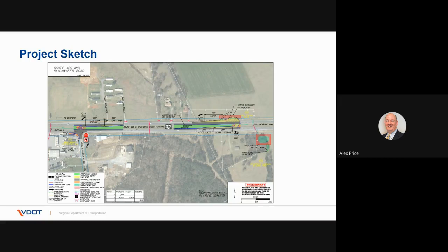Dimensions are shown on the proposed turn lanes, and let me just make a comment there. We need to make sure all dimension aspects of our design are documented and justified, especially when these vary from our standard requirements, in this case for left and right turn lanes. We need to understand what design vehicle was used for the design. That's usually accomplished using auto turn sketches, and those sketches would be part of your submittal as well.